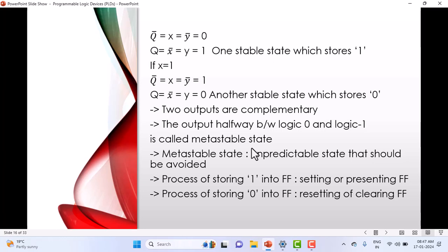They may ask me in the examination, what is metastable state? In the metastable state, you don't see a perfect 1, you don't see a perfect 0. I told you, right? When you apply an input of exactly 2.5 volts, it's neither 1 nor 0. If you apply such a state, can you expect what the output is? The output will also be in the intermediate. It will not go to 1 or come to 0. It will be an intermediate state. What is that state called? Metastable state.